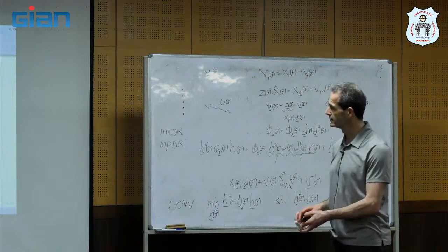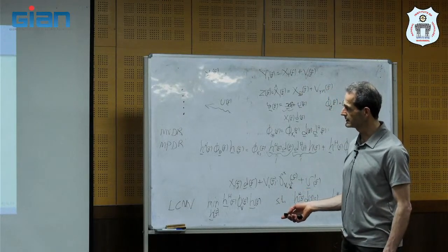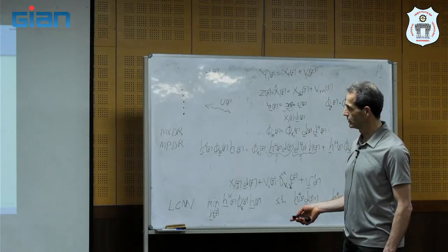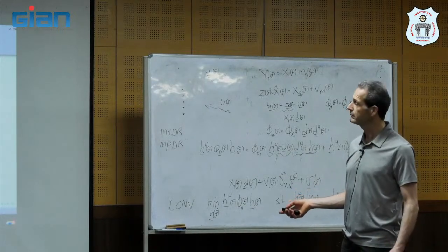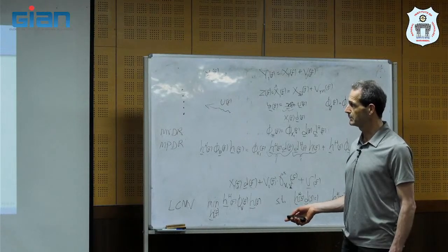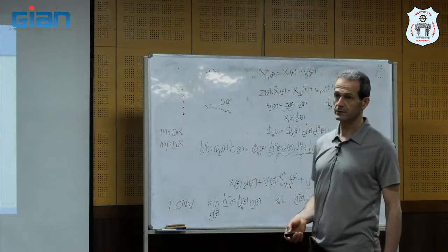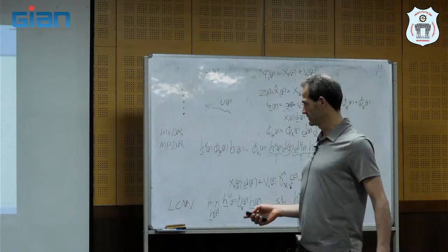Instead of phi y, we can put phi v. In theory, it's the same LCMV, but instead of minimum variance, if I put here y, we can call it LCMP, linearly constrained minimum power. In theory, it's the same. In practice, it's not the same.